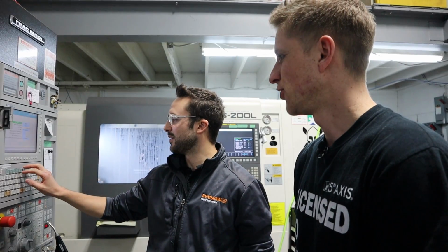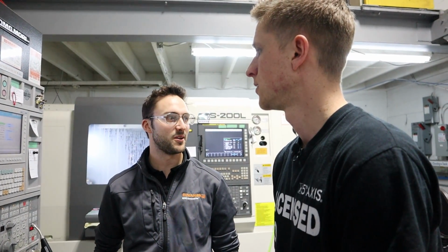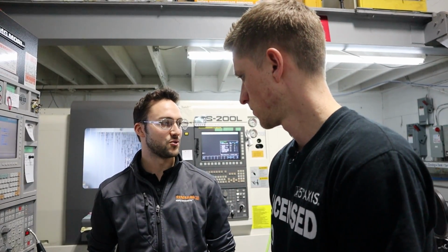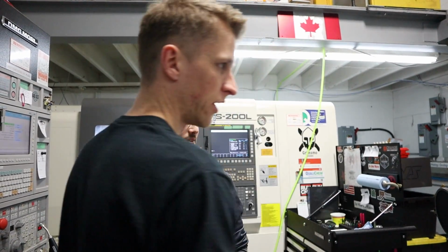Okay. So that you can pull your data, whether it be probing, tool offsets, macro variables, you know, all the important information. All the data. Make your life easier. Okay. And you're just about there, right? Just about there. Yeah. We've got the two talking to each other, and we're just doing a test now to your computer so that we can drop it all out. Okay, so you set up FileZilla on this computer, which is going to be the server. Yeah, so explain how that's going to work. So with Fanuc controls, there's a bunch of different ways that you can store information.